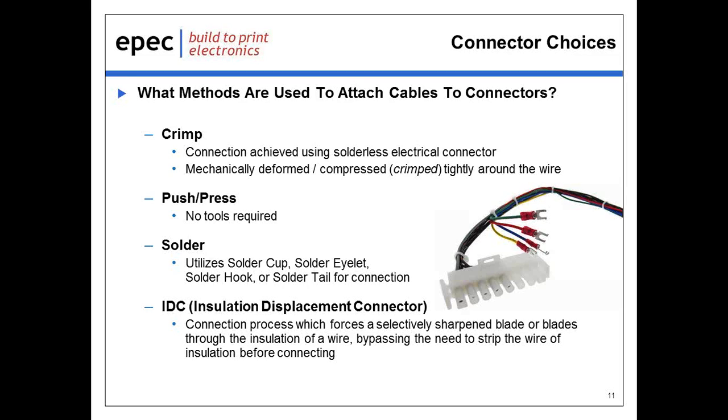Solder connections, when performed properly, are probably one of the better, most reliable connections available today. Soldering can be used on cables with both stranded and solid conductors. Solder connectors usually have a solder cup, a solder eyelet, a solder hook, or a solder tail that's used to attach the wire to the connector.